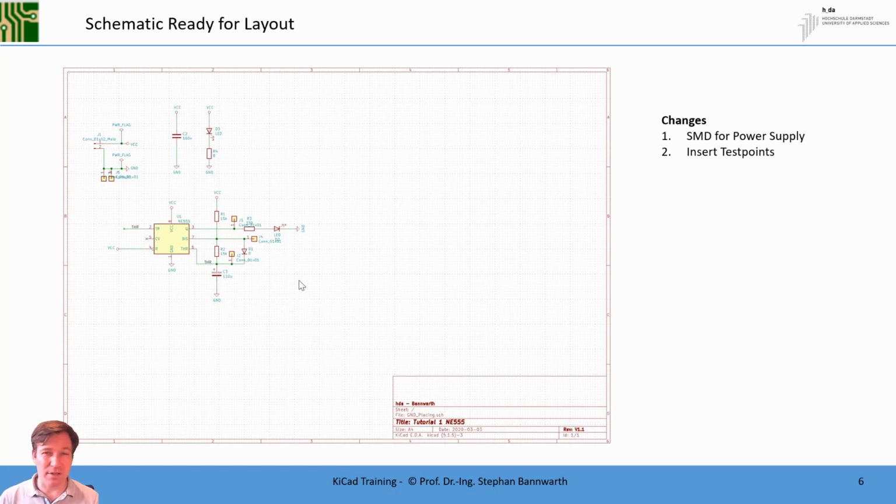So might be it's interesting to see what's the voltage across the capacitor or at discharge and threshold pin. So you see I ended exactly at this point I mentioned, test points. This is the threshold signal, this is the discharge pin, and here we have the output of our circuit. These are the three signals we want to test in our powering up of our circuit.